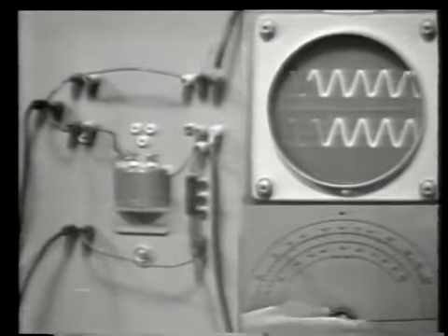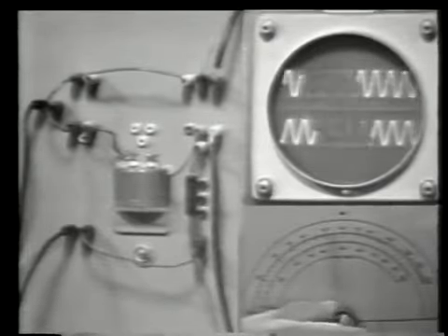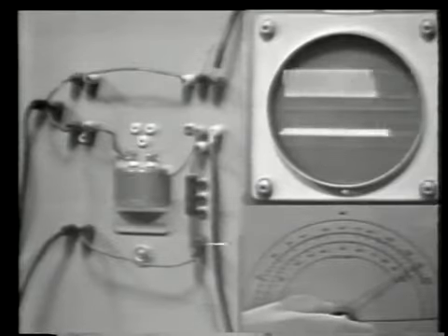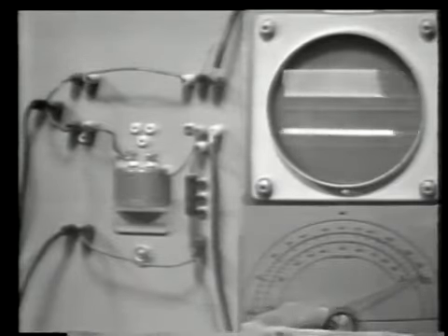As I increase the frequency, though, you'll note that at about 600 hertz, the output starts dropping off. Now we're beginning to reject higher frequencies, which again the low-pass filter must do. Here at about 1200 hertz, you can see that I hardly have anything at all in the output. So we're rejecting these higher frequencies.